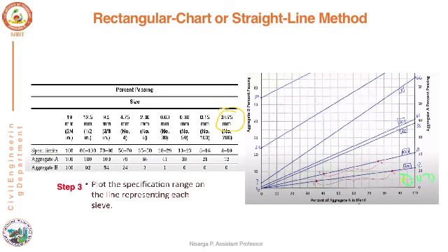How do you draw the specification range? So now for the 0.075 mm sieve, the specification range is between 4 to 10%. Now this value has to be plotted here. Now how do you do it? In the same line, you have to check where we will have the 4% line. If you check here, the 4% value will come somewhere here. Okay, and similarly the next value will be 10%. So the 10% value will come here.